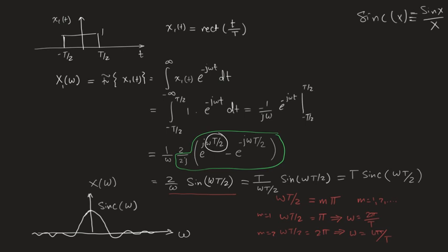Now, why does any time limited signal result in expansion in frequency that causes you to reach even very high frequencies, something like a frequency of infinity? Because any time limited signal will always encounter a point where the signal just stops abruptly, right? Even if it is dropping with a slope, there is a point of discontinuity where it will just stop at 0, right?